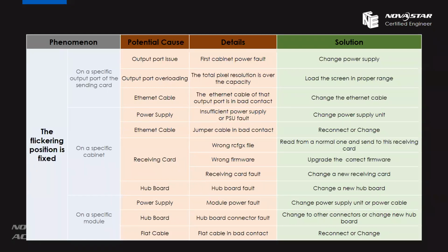And also the hub board could be the reason. And if it's a specific module, it's the same, we need to check the power supply of this module. Maybe it's a power supply cable or the power supply connectors. And also the hub board, the flat cable.